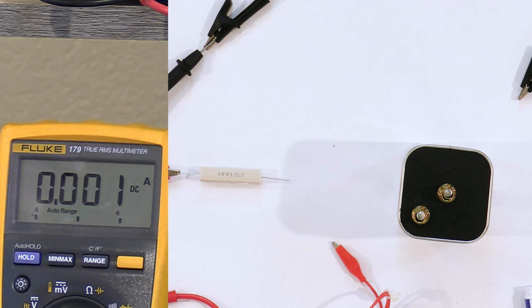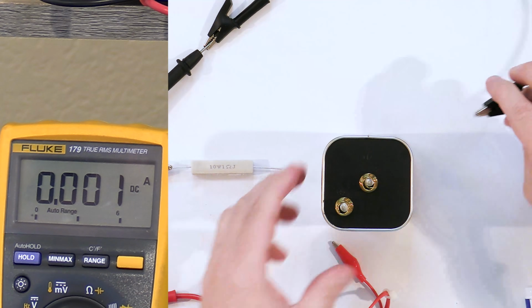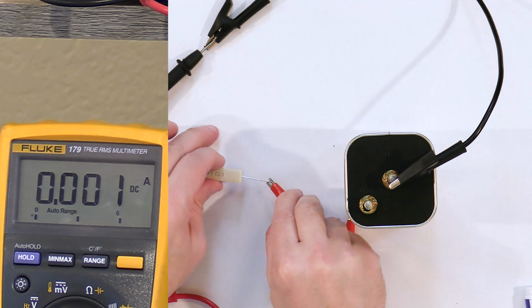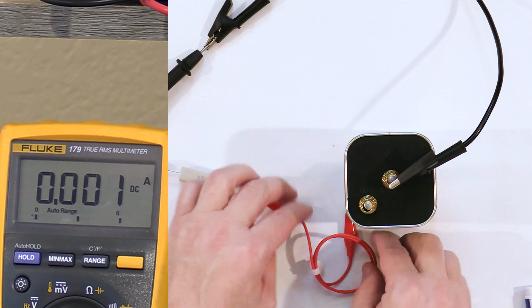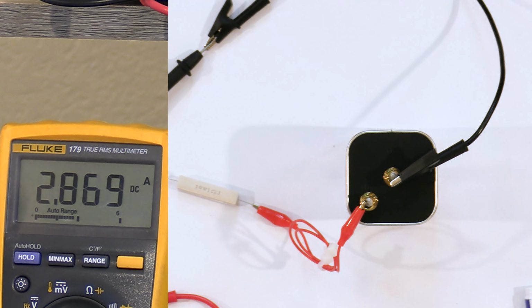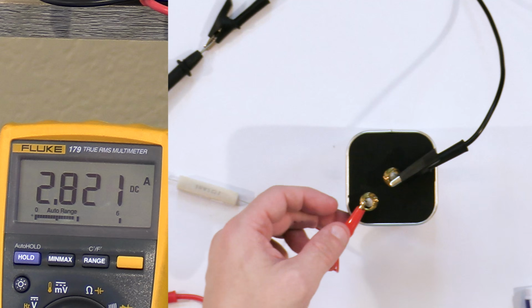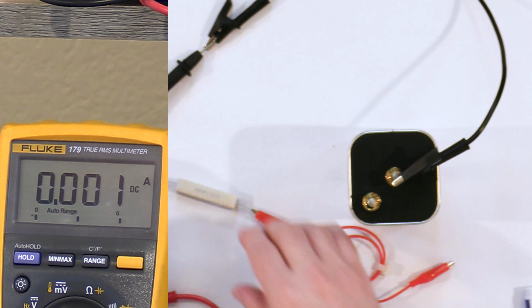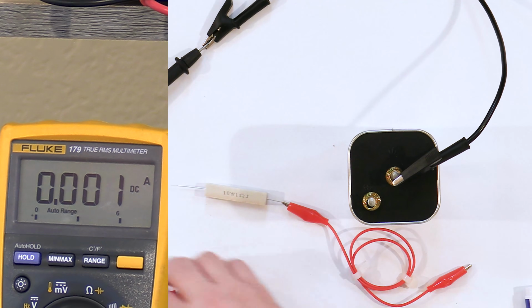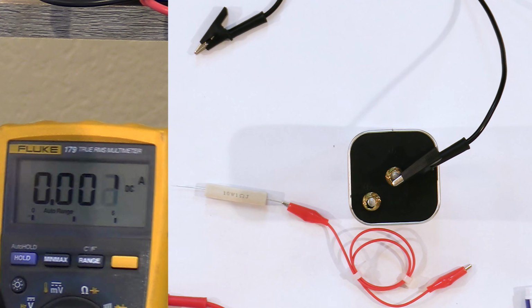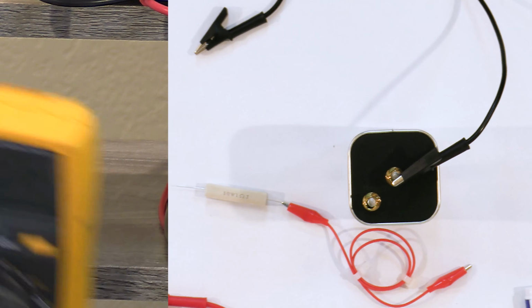I think the simplest way to show you is to reconnect the 6 volt battery to it. So what I'm going to do is connect this here, and we've got it going through our meter over there, right? And we're going to verify again what's going on. We're only getting a little bit less than 3 volts. So what I'm going to do now is disconnect the probe so I can measure the voltage while I'm going to reconnect the circuit, but without the meter in place.